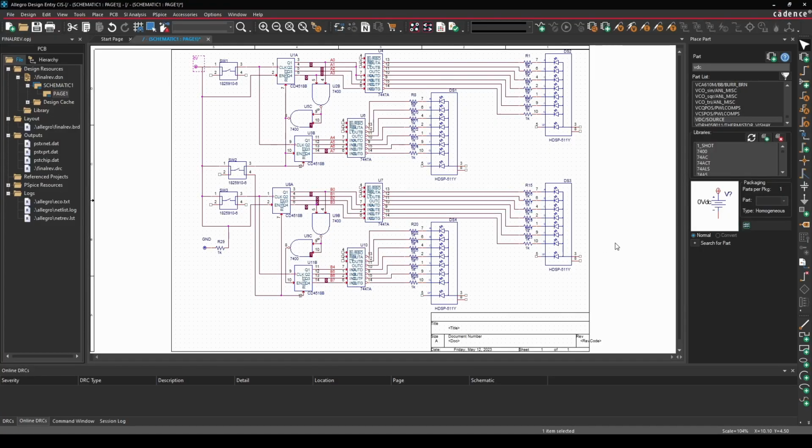Today we will be creating a PCB in PSpice. First of all, come over, look for your DC or AC sources, delete those and replace them with jumper pins. So jump 1 and jump 2 are 1 and 2 pin jumpers for PCBs. So you will replace your sources with these.